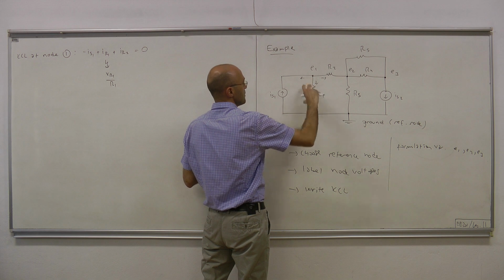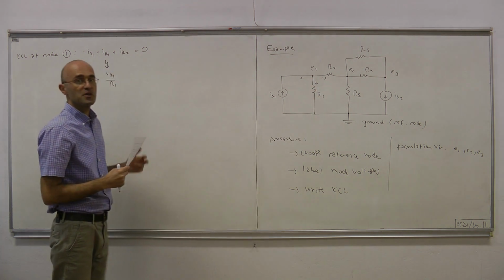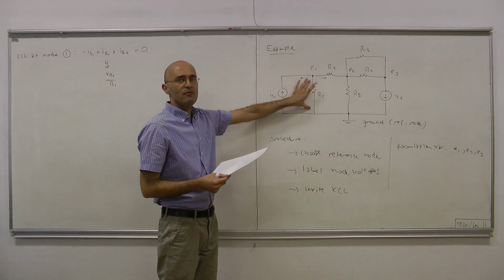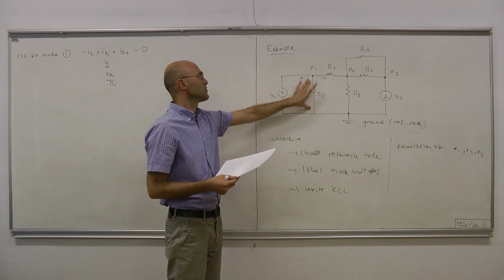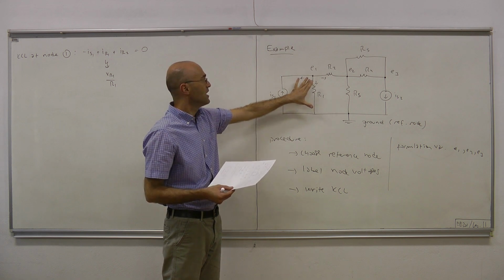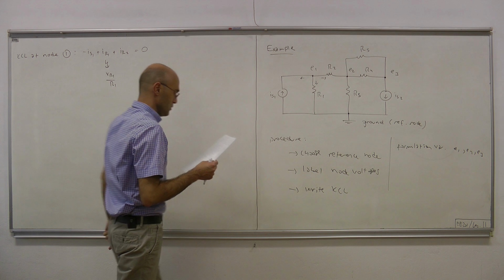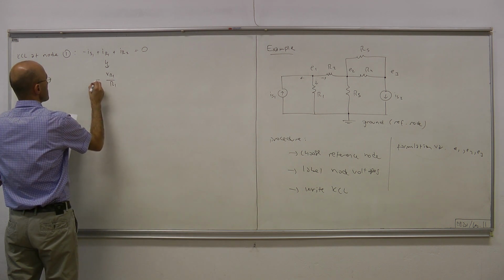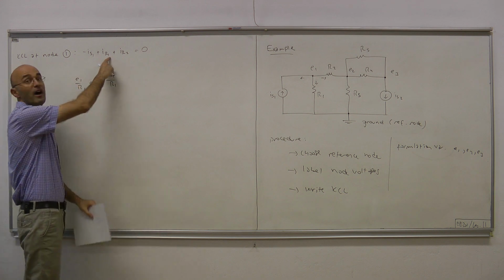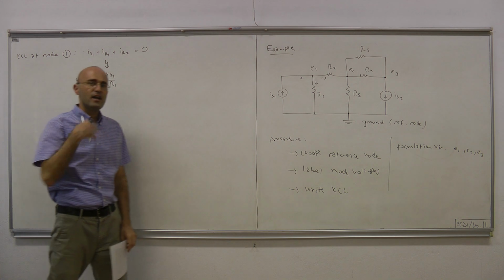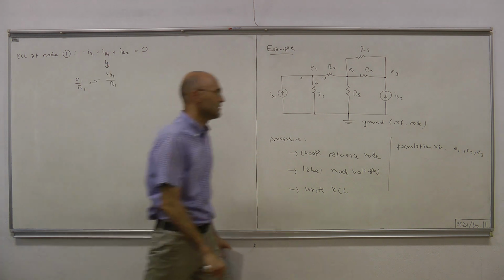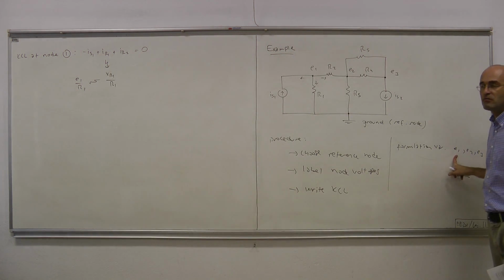And VR1 is this voltage, plus minus, the voltage that appears across the terminals of R1. And this VR1 is a branch voltage, and we know that we can easily express branch voltages in terms of known voltages. And this branch voltage is no other than E1 because it appears between node 1 and ground. So this thing here is E1 over R1. Therefore, instead of IR1, if you write E1 over R1, everything will be fine because R1 is known. We assume we know all the circuit parameters, and the unknown E1 is one of our formulation variables.